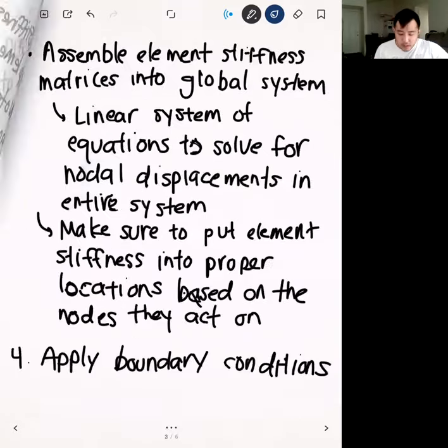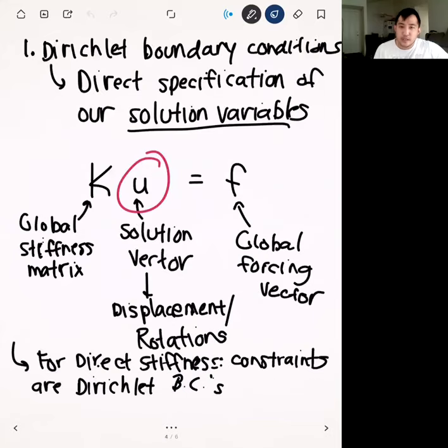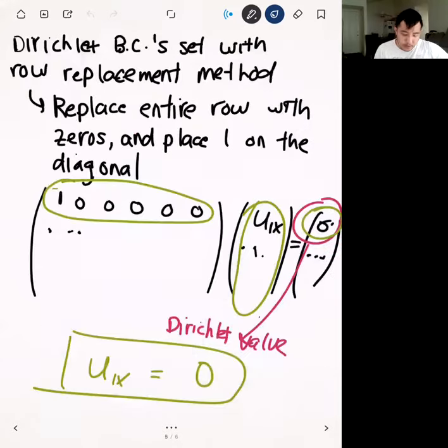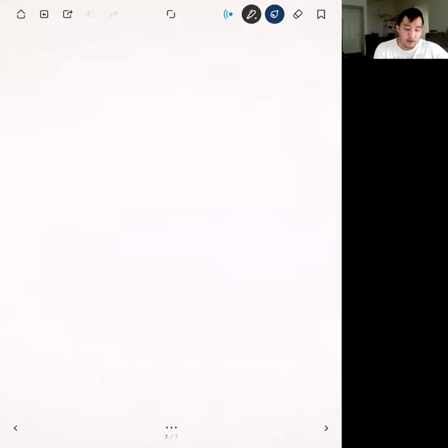Okay? And so once we get to 2D problems within the more general finite elements, you'll see that it's going to depend on both the equation and the type of element. But for now, everything that we've been doing up to this point with direct stiffness, you can think of as one-dimensional elements. I know we've been doing 2D problems, but our elements themselves are just like sticks, right? So they don't actually have a thickness or anything like that. They have a cross-sectional area, but that's just a parameter that we specify. But then later on, once you get to 2D, especially for your project, that shape is going to be really important.